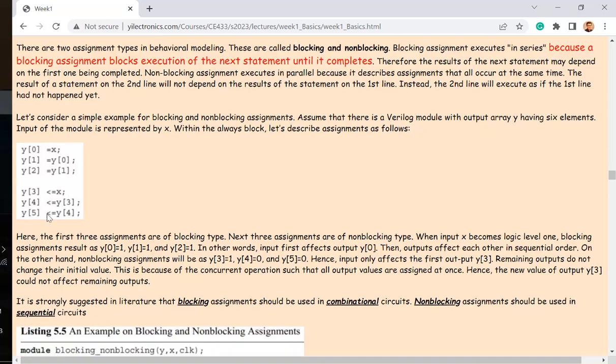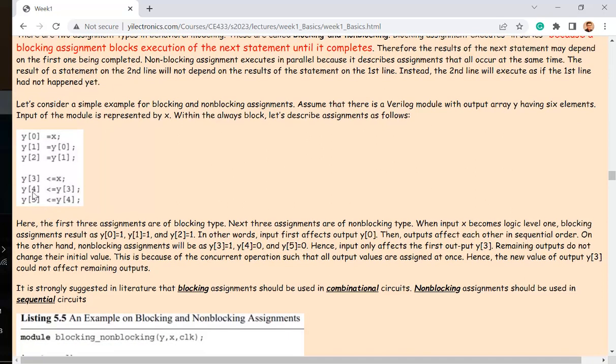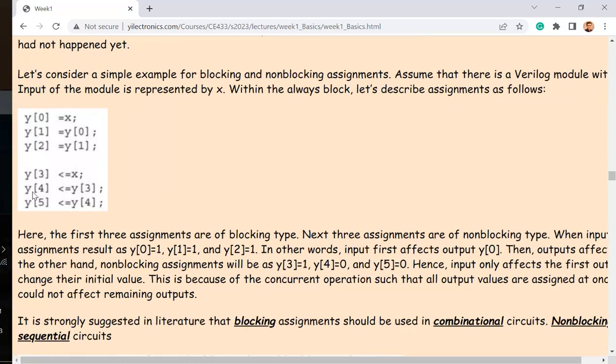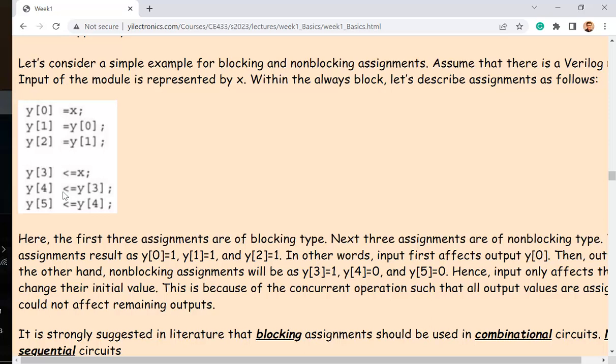What about the other one? There's a non-blocking assignment. How do we understand it? It's like a parallel in, parallel out register, a shift register. You give a clock to the three of them. The data is getting through the three flip-flops at the same time. So it's not waiting for any changes, actually.